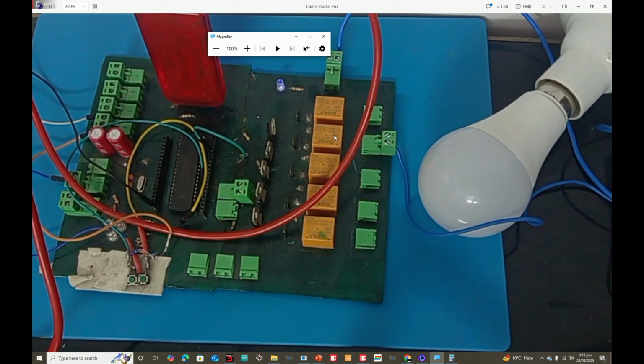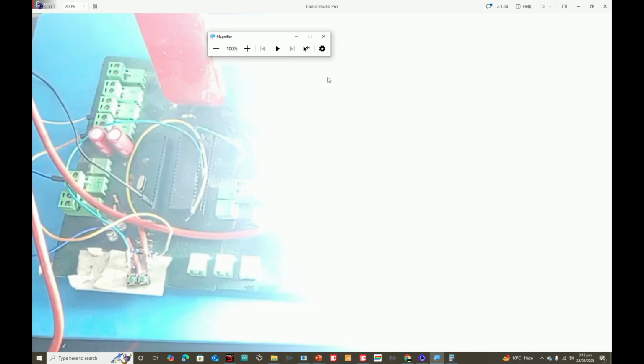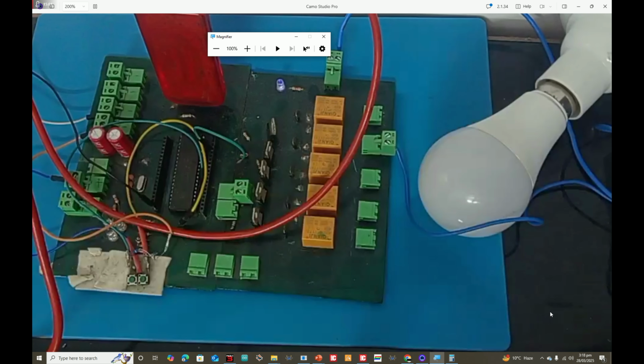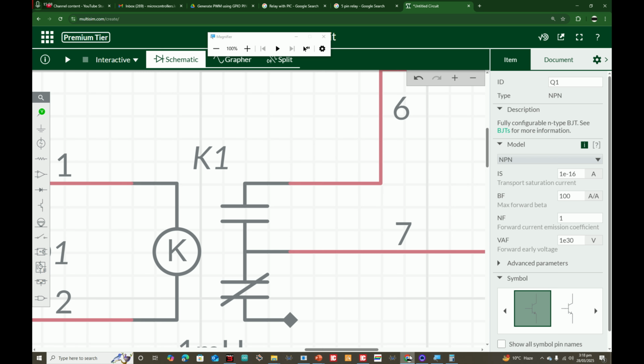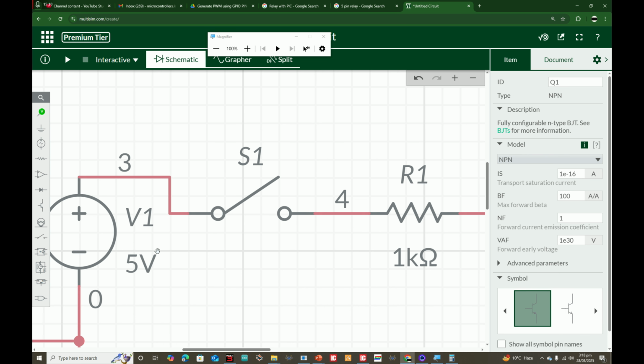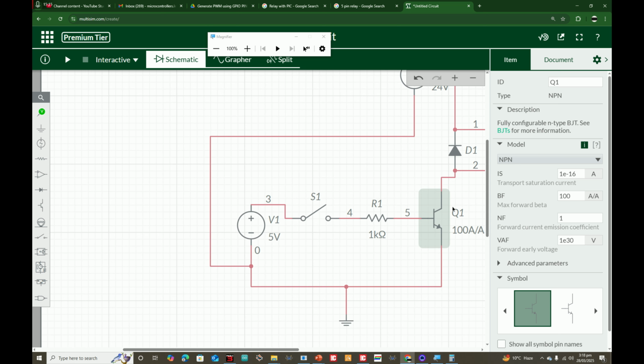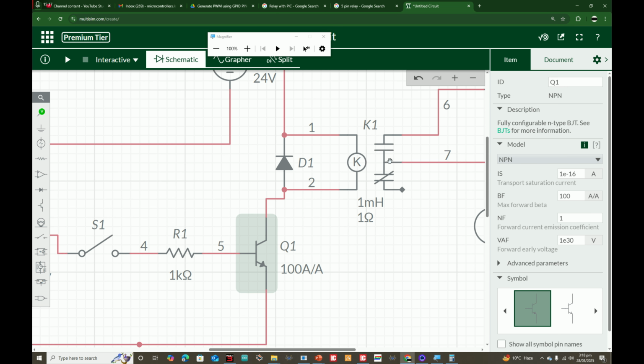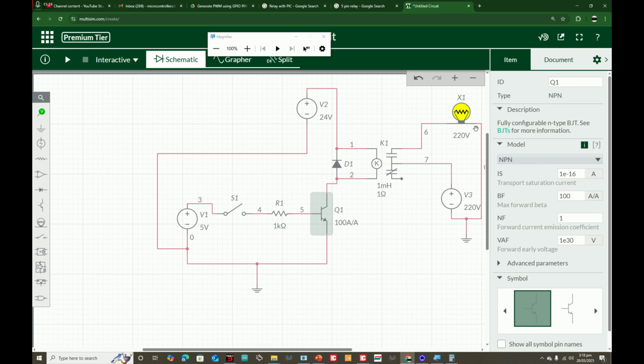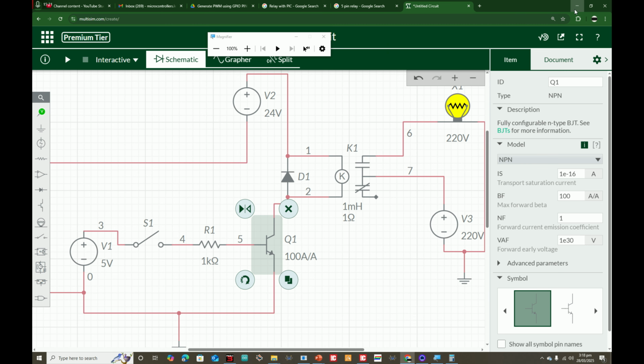Relay can support a current of up to 10 ampere, this small 5-volt relay. So this is the beauty of using these relays. Like, you can trigger a load of up to 220 volt AC and up to 10 ampere, 20 ampere, whatever the voltage, doesn't matter. Your circuit over here is very simple. So again, this is the story here. Here you have your microcontrollers, 5 volt or 3.3 volt. It triggers a transistor. Transistor triggers the relay, and relay triggers your load. Simple.